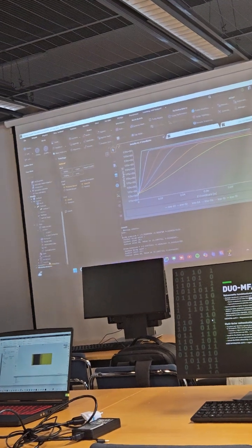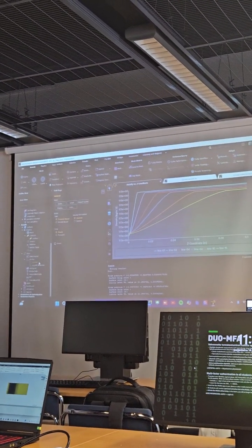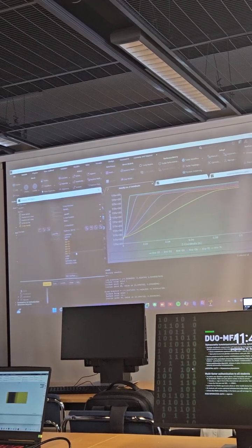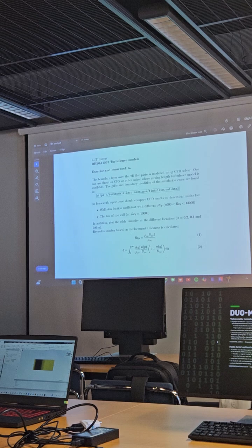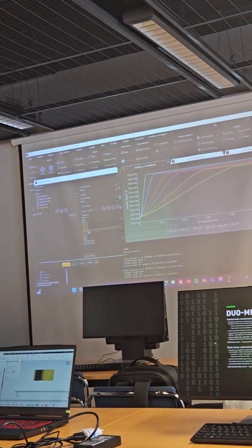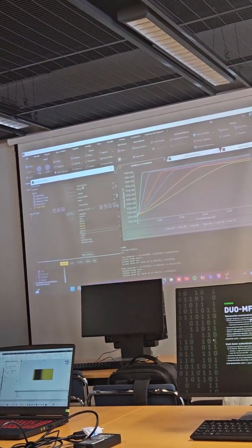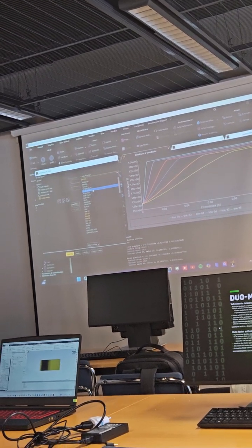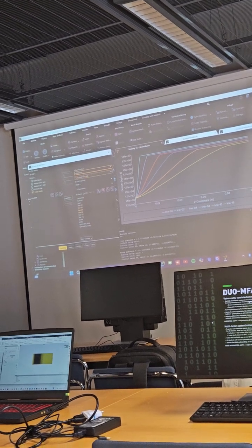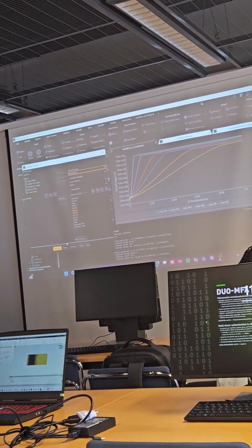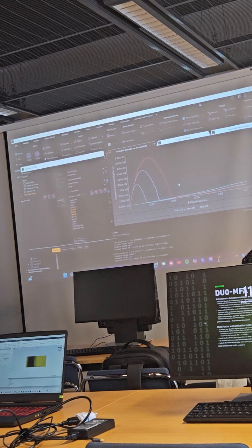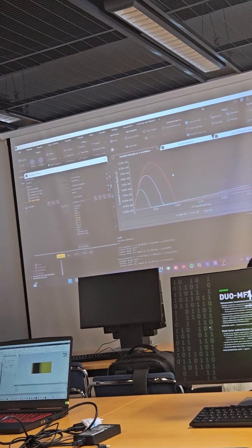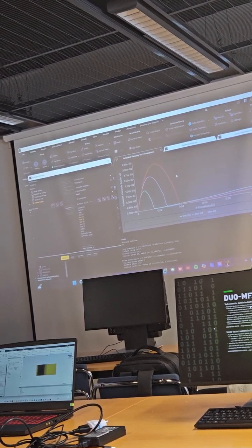So in Fluent, again, I take this plot for the different lines. So we are at 0.2, 0.4, and 0.6. And the variable for the eddy viscosity, you can find it in turbulent viscosity. So that's the eddy viscosity. And you can plot. So now you can see also the distribution of the calculated eddy viscosity as a function of z for these three x locations.